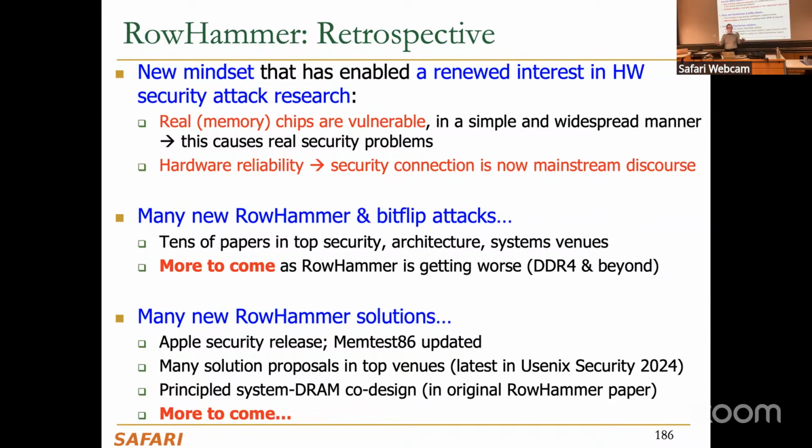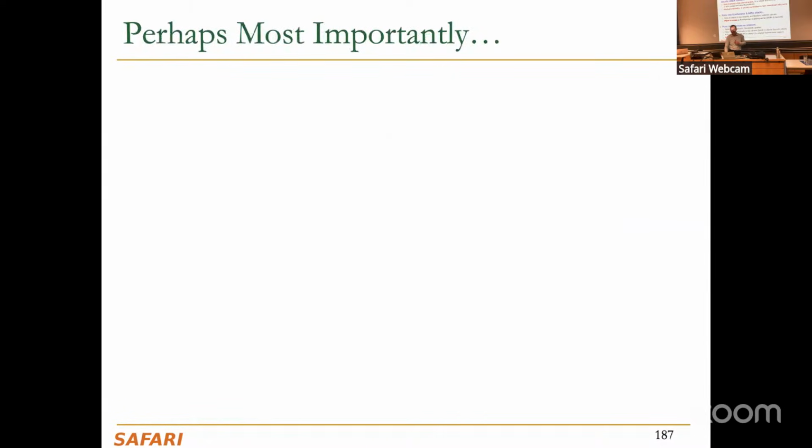Now, if you actually have per row activation counters, it's going to be even harder to induce the bit flips. I don't think they will get all the corner cases right. So there will be some way of inducing these bit flips, but it will probably take a lot of time to induce them. But RowHammer solutions are still very good to develop, and trying to actually induce these bit flips is still good to do. And trying to understand the device level, or the vulnerability at a fundamental level, like testing in a lab, is still very useful because that can enable other vulnerabilities to be discovered.